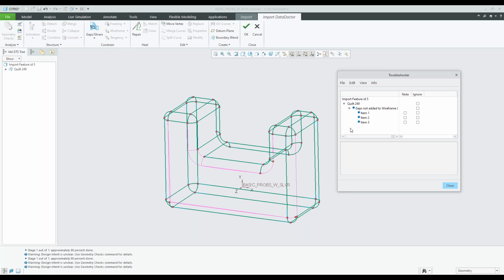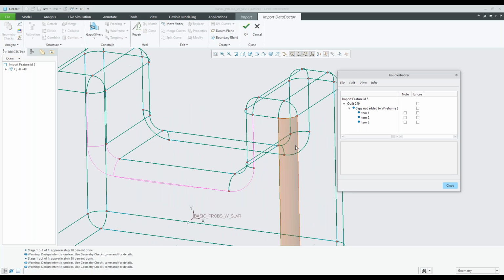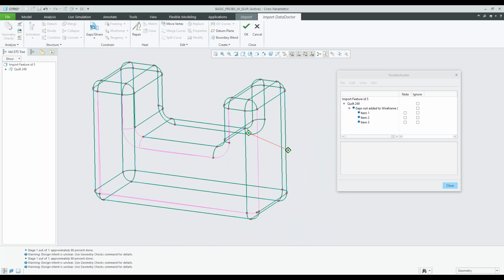Then you need to spend time on it, fix it, and get more than one version from your customer or from whoever supplied you with the step file. Play around with that. Spend some time initially finding the best method to start the repair issues. Work through different scenarios, and don't repair everything in one go. Start working with that model, do bits and pieces, recreate surfaces if you need to.